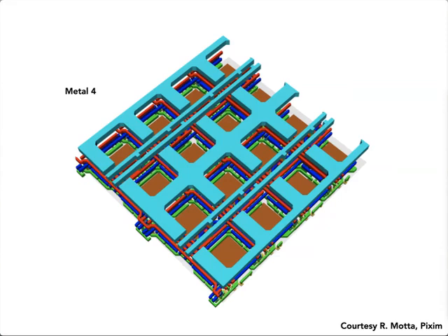If you start thinking about this, thinking back to your work on ray tracing or your knowledge from camera design, the light needs to flow optically through to the photosensitive part. So you might notice a bit of a problem here: we've built up, in a stacking volumetric sense, a whole bunch of structure that's going to block light from getting to the photosensitive part. So now we have a bit of a tunnel. Can you see that each of these photosensitive parts is at the bottom of sort of like a metal tunnel? That's a problem from a photon capture perspective. It's a practical, optical challenge to get the light to where it needs to go. We'll come back to that in a second.